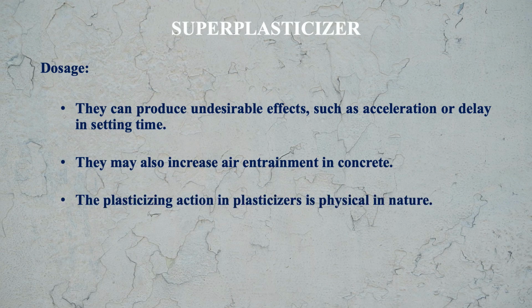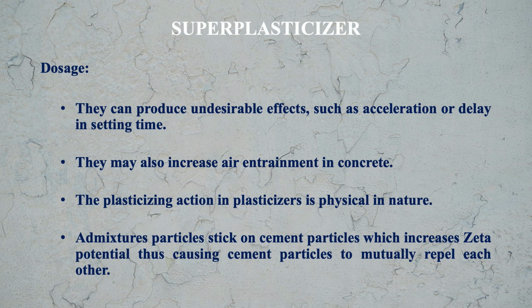The plasticizing action in plasticizers is physical in nature, means no chemical reaction is taking place by addition of these admixtures in the concrete. Admixture particles stick on the cement particles, which increases zeta potential, thus causing cement particles to mutually repel each other. Means repulsion comes into the picture, and this repulsion is because of the zeta potential created by the admixture particles which are sticking on the cement particles.